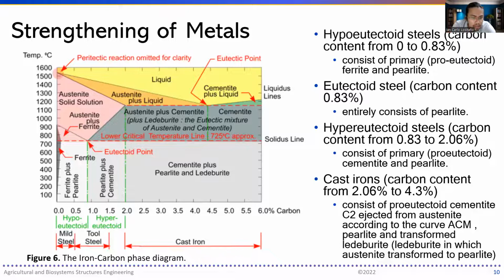So this is the iron carbon phase diagram, and based on the temperature and the percent of carbon, okay, one could achieve the various phases of steel, and it would create a different steel because of the different structures of the crystalline lattice structures in the metal. There would be a lot of differences in the properties.